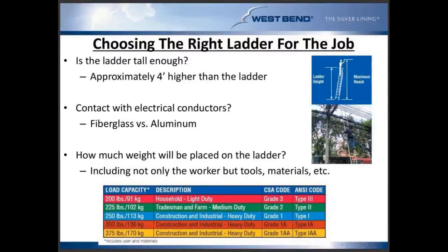So one of the first things that we need to consider when we're talking ladder safety is, are we choosing the right ladder for the job we're performing? And like I talked about before with the OSHA violations, one of the most frequently cited requirements that they have is employees using ladders on the top or top step of a step ladder.